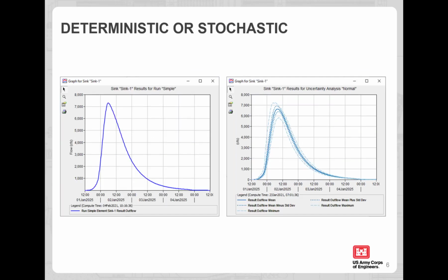We've talked about how, for each hydrologic process in HEC-HMS, there's a range of mathematical model options. The reality is that each of these modeling options is deterministic. In a deterministic model, we fix a set of parameters and initial conditions, and the model runs. There is a Monte Carlo simulation option in the program that allows us to take a deterministic model and create probabilistic output. One of our ongoing research areas is a probabilistic parameter estimation tool that allows us to estimate uncertainty in model parameters.